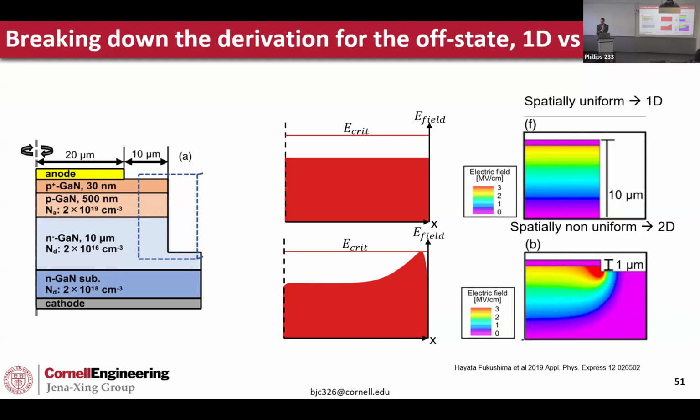If you do a DIT study of different oxides on different surface planes, you get different values, and the quality of that interface is going to change. So the principle is the same in all of them: you want to move charge as well as the electric field lines away from that edge. But each material has its own specific nuances, like nitrogen polar versus metal polar that you have to work around, or the faceting, like you said, with different surfaces.